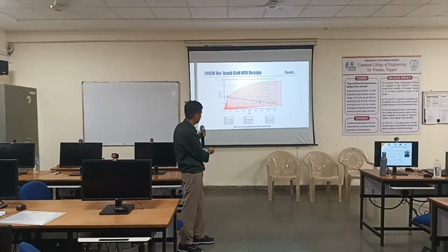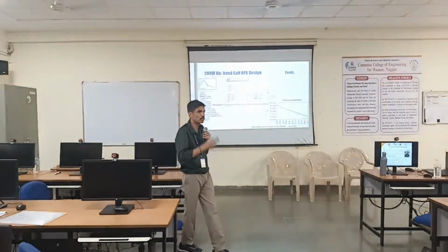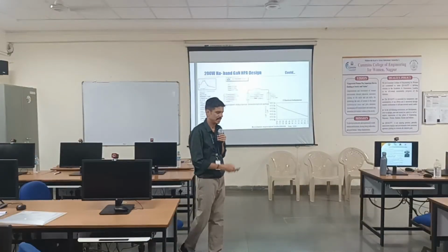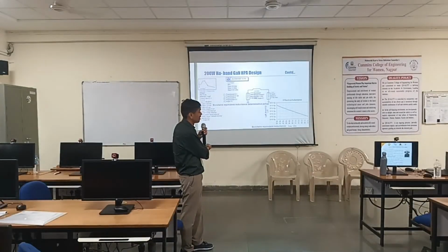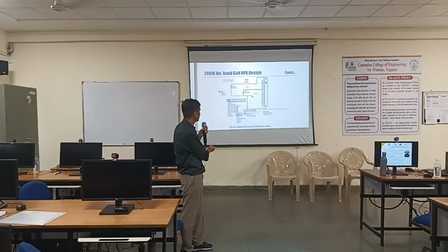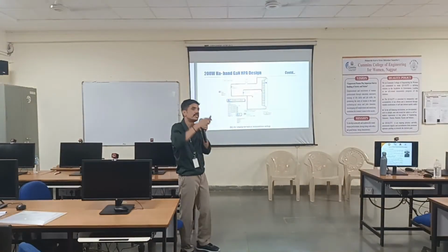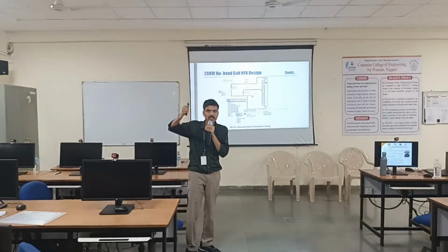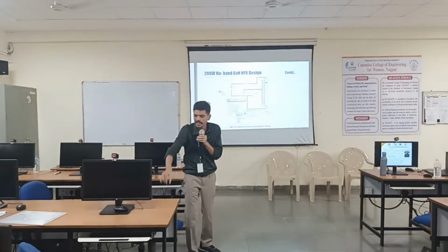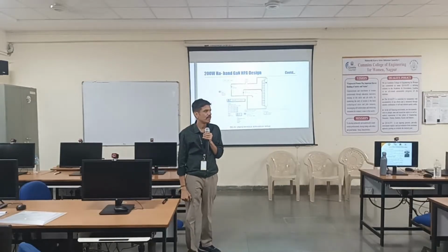Then I did the same practice. Because my target was 200 watt, 150 watt, so 5 watt will not do anything. This is another problem. Because you had 16 gates, you will have 16 pins of actual transistor. Your transistor will be this much big. So how do you connect on PCB? You cannot connect a single pin on the microstrip.